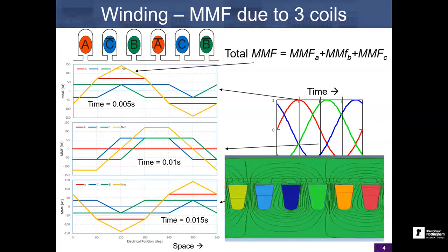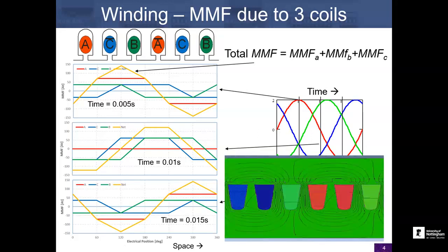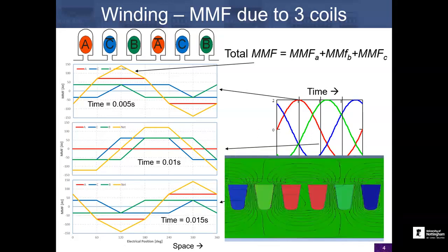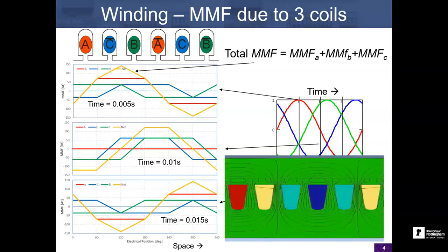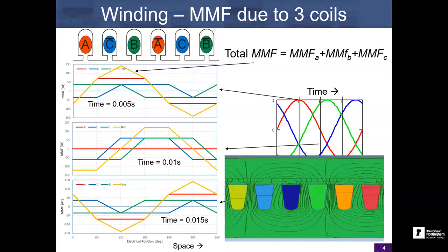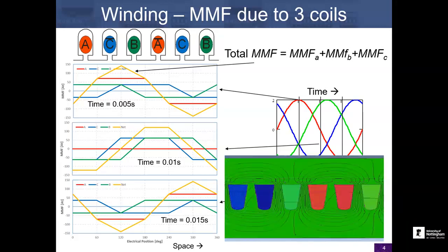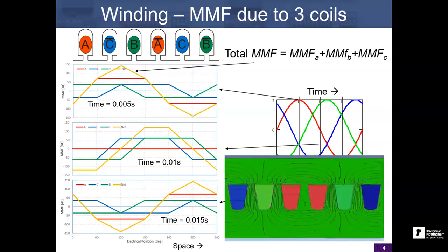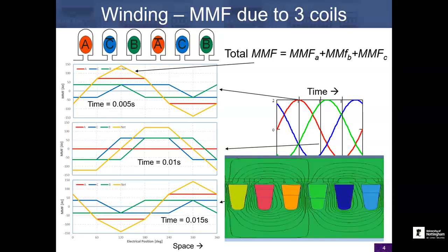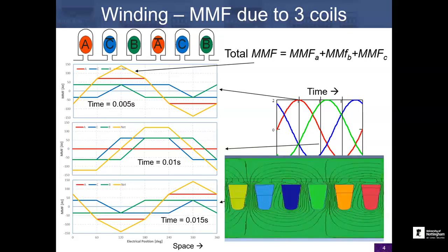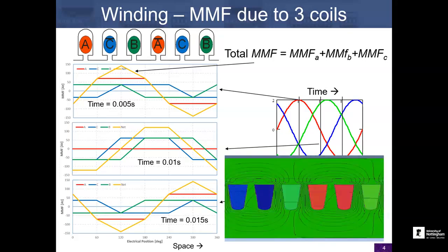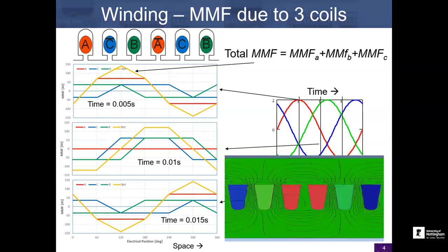So our field travels along the air gap of the machine, our current distributions, our flux densities are moving at a speed fixed by the frequency of excitation of the current. And this is a fact we exploit in induction machines, in synchronous machines, in some kinds of reluctance machines to give us travelling behaviour, to give us behaviour and output power.